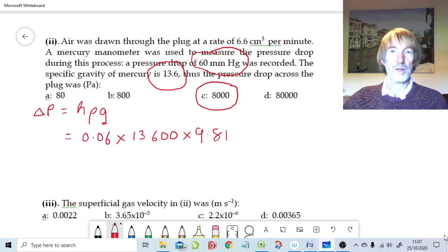centimeters cubed through that porous plug in part 1, the pressure drop that's measured in a manometer, that's just a simple two tappings either side of the bed, and looking for the difference in height of the surfaces of the manometer, gives us 60 millimeters, which converts to an SI pressure of 8,000 pascals. So we're getting to the bits that we need for the Kozeny-Carman equation.